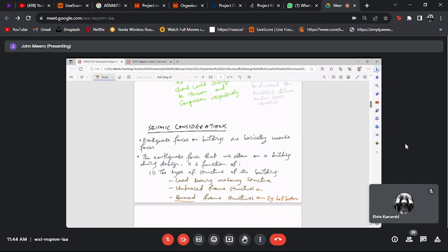If a structure has not been equipped with these very strong reinforced concrete walls, or cross bracings for steel structures like water tank towers, the ones that they build nowadays out of structural steel, you see they have cross bracings all through. So that's a braced structure. Now, if a structure is not equipped with either a shear wall or a set of bracings like in those elevated water tanks, we call them unbraced frame structures.